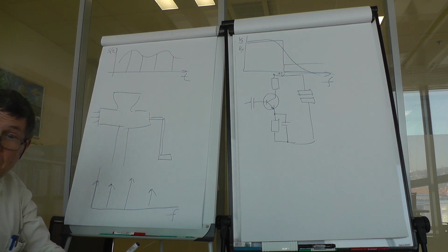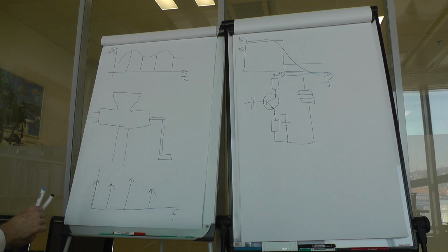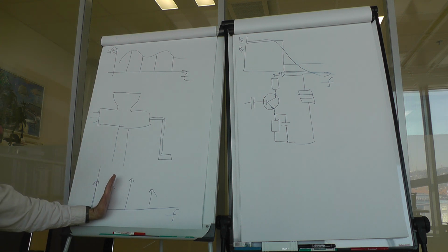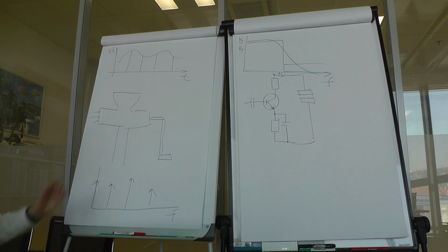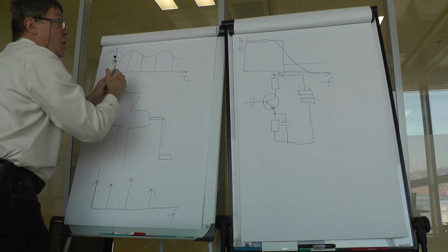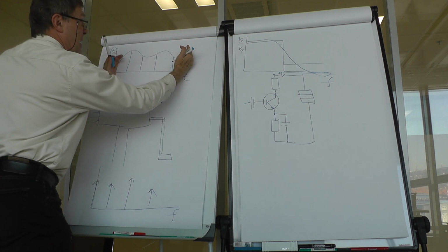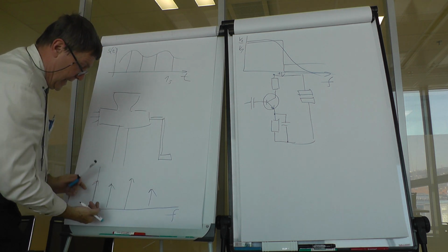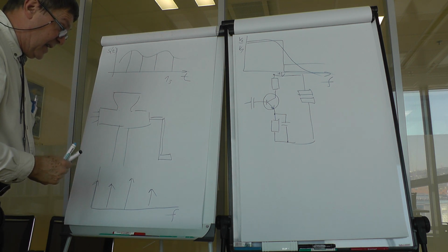And of course we have phases. So we have a set of components with magnitude and phase shift at each relative frequency. Now the basic frequency is given by the interval we sample. So if we have 1 second of time sampled, we get a 1 Hz component as the basic one.